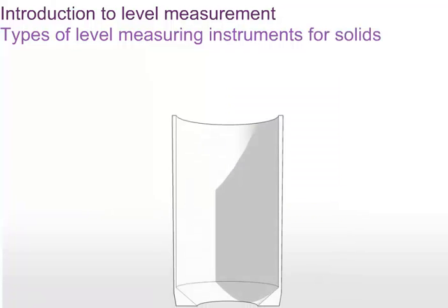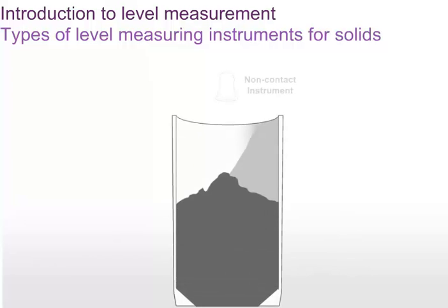When dealing with certain types of material, non-contact level measuring instruments are more reliable. This is especially true if the material being measured could cause damage if it came into contact with the instrument. Also, contact-type instruments that rely on a wire touching or penetrating the material surface can fail if the wire becomes buried or snaps under the material load. For certain materials, non-contact is preferred to prevent any risk of contamination.